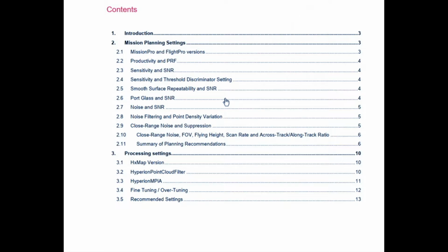The impact is that you get a very high back reflection, which can even damage the receiver, the APD. Besides this, every time the laser ray goes through the surface of the glass, out the upper surface, out the lower, and then the return comes back, if the glass is not coated, you can lose up to almost 20% of laser power.